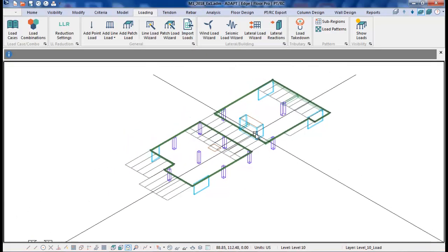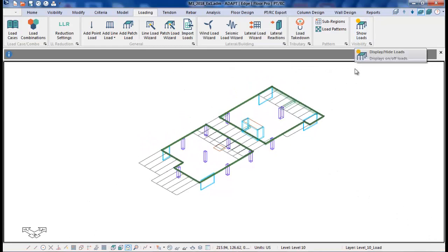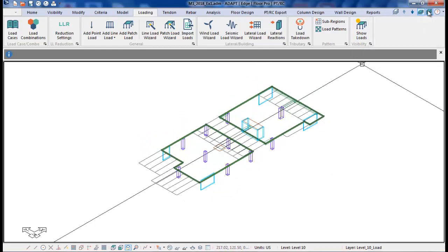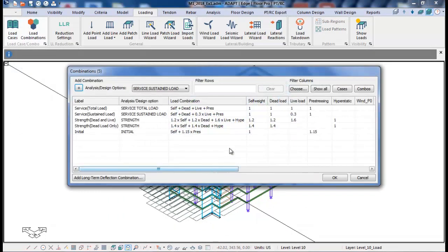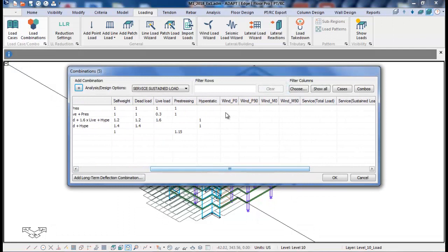And these loads on the slabs now, this set of loads for wind P0, for example, can now be included as part of a load combination. So you can see those are listed here as individual loads. Now, the program currently does not generate the set of load combinations necessary to meet the ASCE load cases 1 through 4, but we can again set those up in one model and then easily import those load cases to a separate model and then save that as a template.